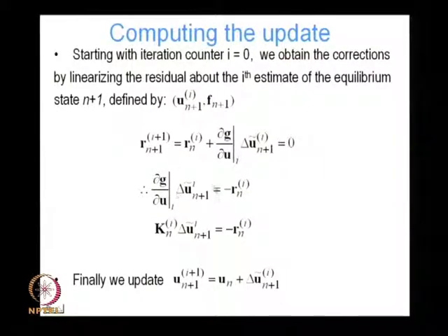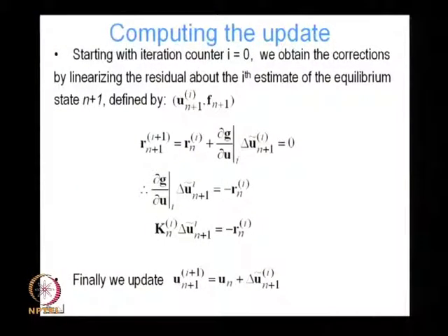So again that gives me the change in the displacement increment. It is like I computed some value of the displacement increment, now I have to change it at each iteration. So you can think of it as change in the increment or increment in the increment, whichever is convenient. So it is the change in the displacement increment delta u n plus 1, and to do that I move this to the right hand side, since this is known, everything at iteration i is known.